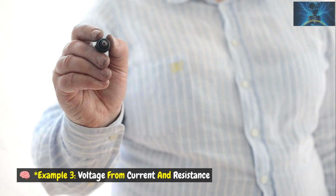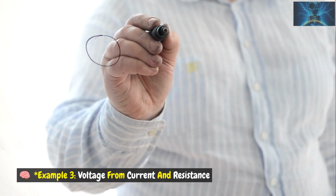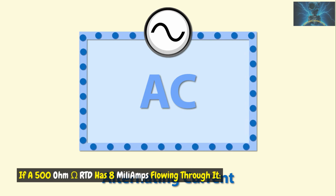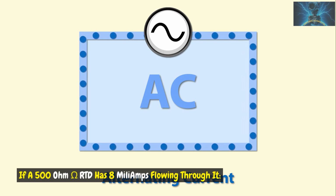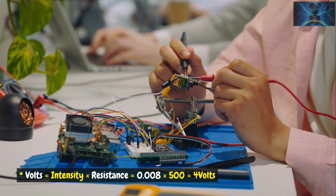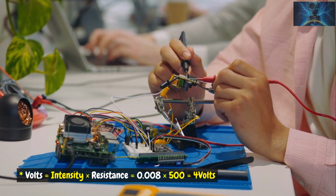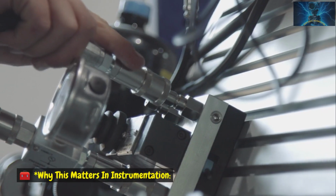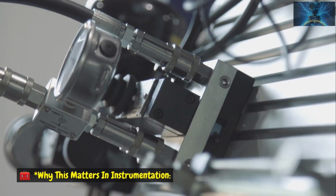Example 3: voltage from current and resistance. If a 500 ohm RTD has 8 milliamps flowing through it, volts equals intensity times resistance equals 0.008 times 500 equals 4 volts.